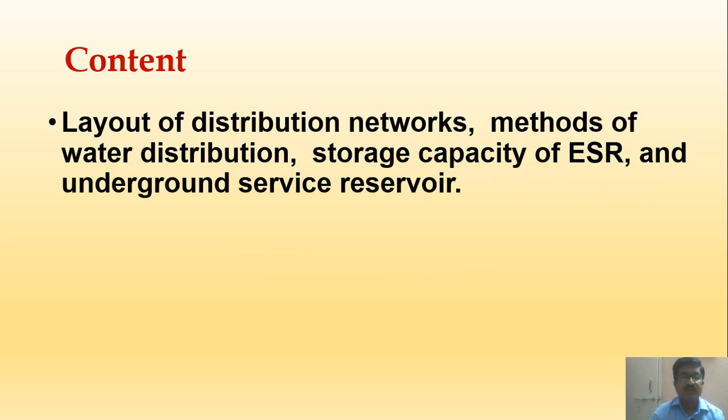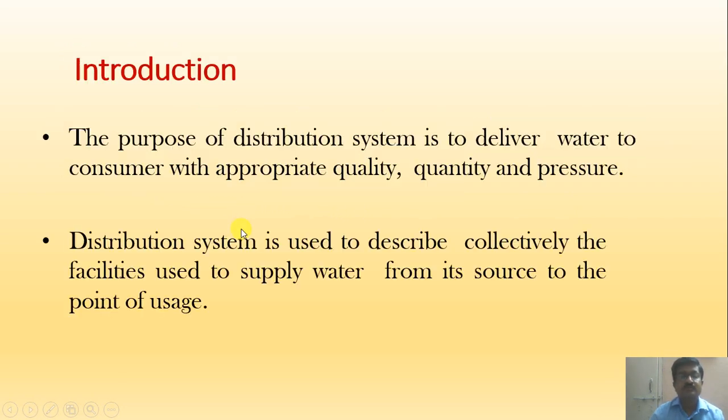So the overall content of today's session will be the layout of distribution networks, methods of water distribution, and storage capacity of the ESR, elevated service reservoir, and also the underground service reservoir. Now, the purpose of a distribution system is to deliver water to the consumer with appropriate quality, quantity and pressure. The distribution system is used to describe collectively the facilities used to supply water from its source to the point of usage.